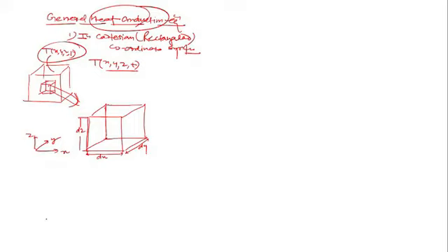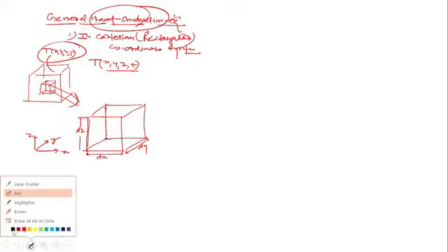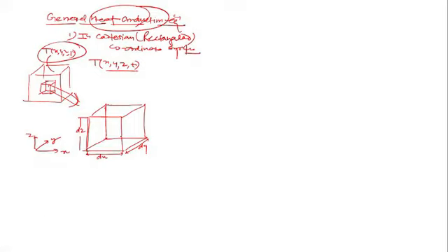And over this element I will apply the rate of heat transfer by conduction. So my dear students, here it's simply q dot x, heat transfer in the x direction. This is the x direction, yes or no? Q dot x, heat gets in, then through this face heat gets out. This is written as q dot at x plus dx.